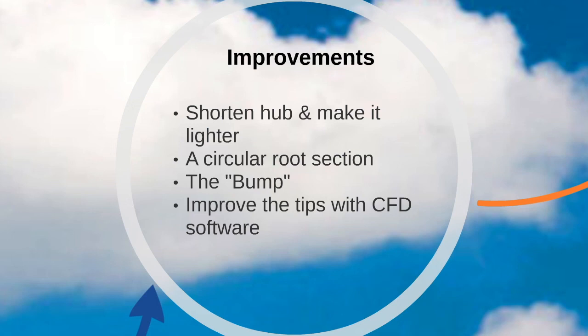The tips were originally designed with the intention of rounding them up with a smooth profile. Further performance increase can be achieved by improving its design using some CFD software. We can also look at using a variation of aerofoil profiles along the blade rather than just one throughout the length of the blade.